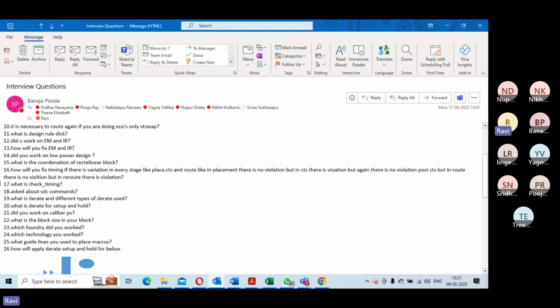Correct. So one is, why is there a high density of current? Let's say a clock net. You have like 100 fan-outs. Why do we do fan-out fixing? Because you have more than 64 fan-out or 100, 200 fan-out.